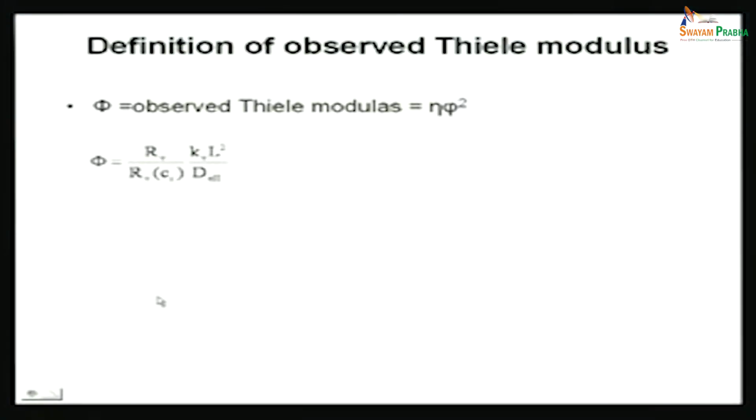So this is what we have on the screen as well, just the same thing that I showed here. What I did was for a general reaction, and what is shown here is for a first order reaction. R_V at C naught is represented by k_V times C naught, and this is what you have. I think this k_V cancels out. Don't worry about this on the screen, I think there's a mistake there. This shouldn't be k_V, because k_V is in the denominator anyway.